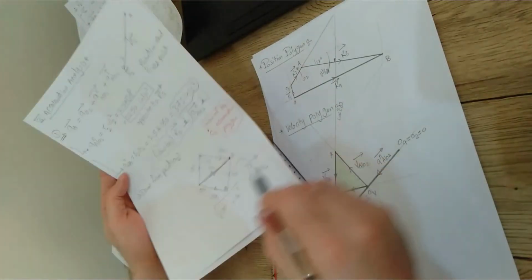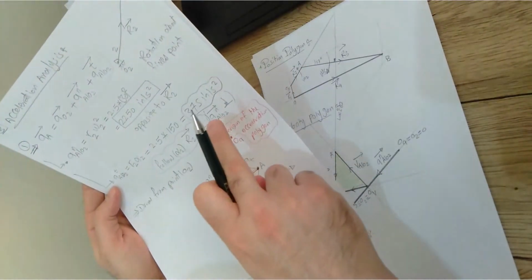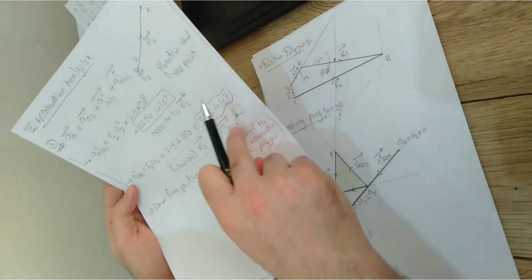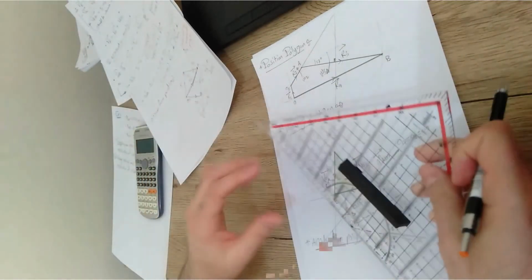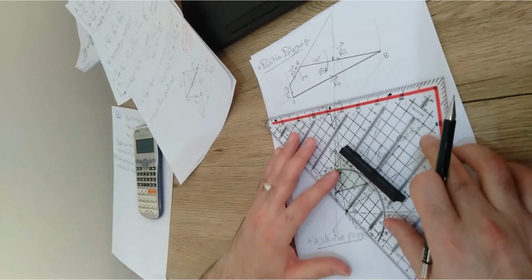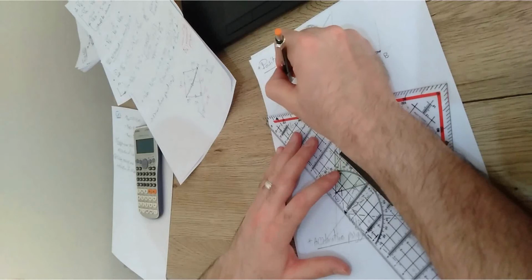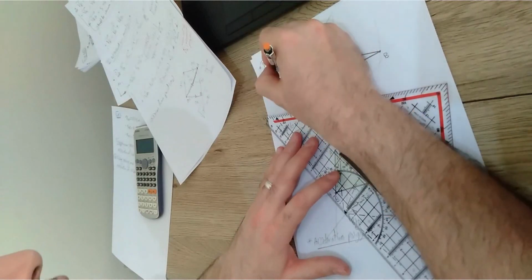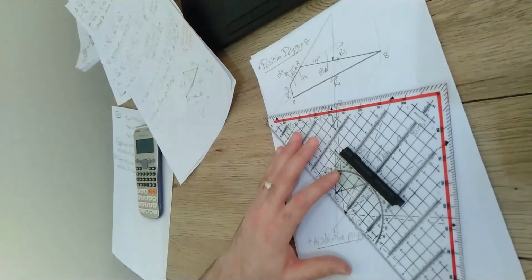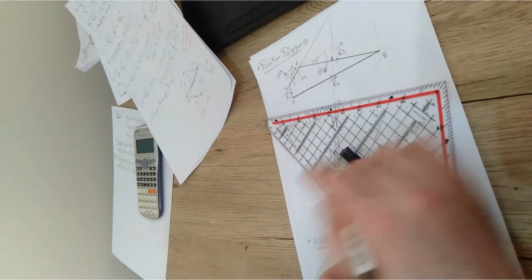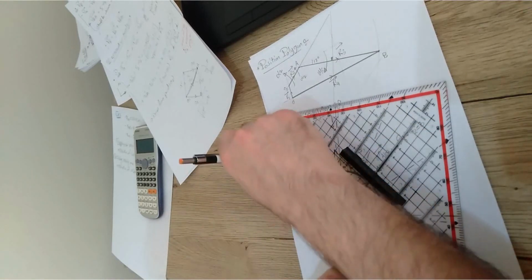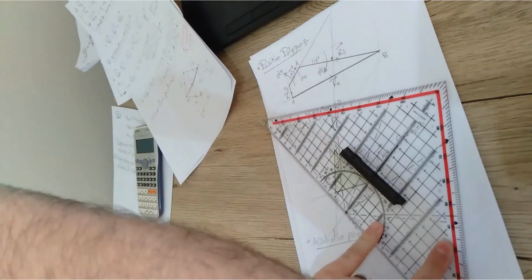What is the direction of R2? R2 is already going up. This is the R2, or simply you can consider that it is normal to the normal component. It is perpendicular to the normal component. So we got the normal component. Draw a line that is perpendicular, following the direction of alpha 2. Remember that alpha 2 goes in the counterclockwise direction, so this should be the alpha 2 direction. It means that I have to go up. So from this point, I'm going to draw a line that is perpendicular going up.